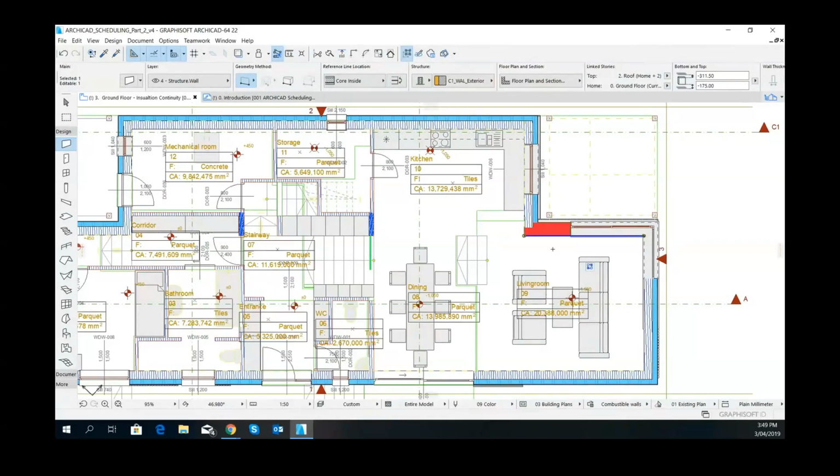So things like finding particular things in a project based on certain criteria, or checking things, making sure that things have been done properly. So if you are meant to be classifying stuff and you want to make sure that whoever's been working on the project has been, you can set up a classification to make sure that certain data has been entered into certain places, or certain criteria have been met. Then it will show up stuff that's not done as red or blue or green or whatever you've set it as, and then you can go in and fix all that stuff up.